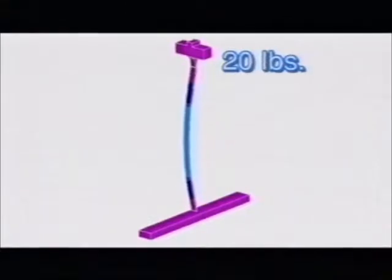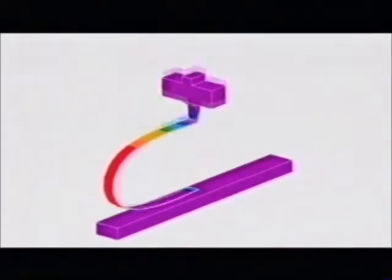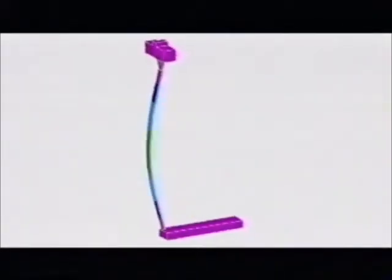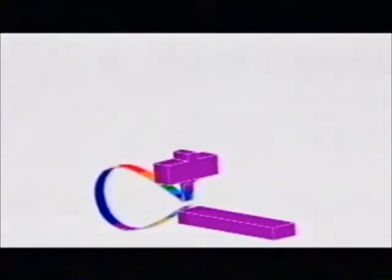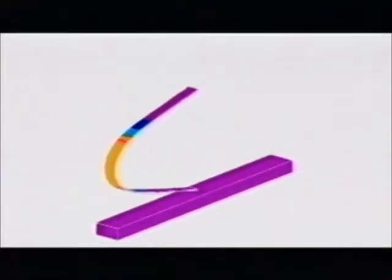And here is the result of the run with 20 pounds. It predicts several things. First, the bar is indeed buckling under the 20-pound weight. Second, a very large deformation has occurred. Third, the bar did contact the floor, which constrained it and forced it into its final shape. Let's further examine the significance of the floor. Without it, we still get buckling, but it is nothing like the correct simulation. Finally, modeling the removal of all the weight, we obtain the permanently deformed shape.